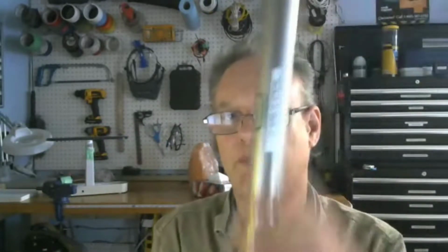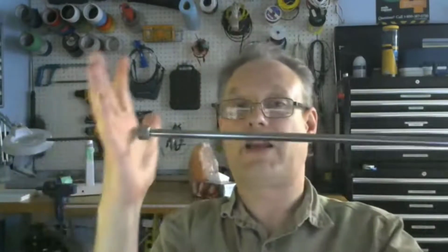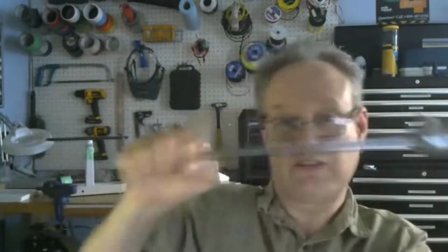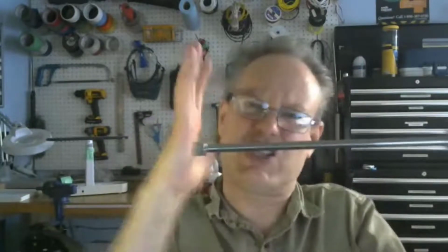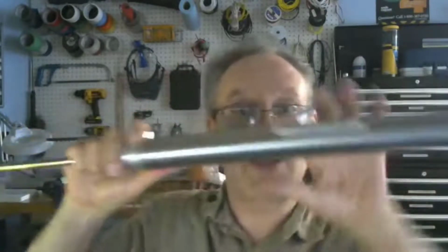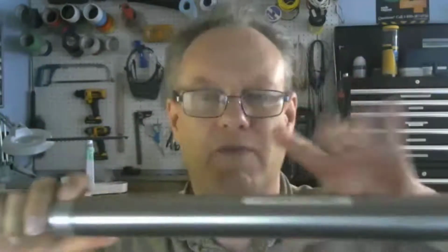So the question was, wait a second, if I used a larger bore diameter, wouldn't that decrease the pressure to a very small degree? Yes. During extension, absolutely, it would decrease the pressure. But the force application is only, I'm going to back it up a bit, because it's clamping force, right? It's only right there, right at the end. When it finally stops, the pressure in here builds up very quickly, and then it meets the system pressure, whatever your pressure regulator is set to.